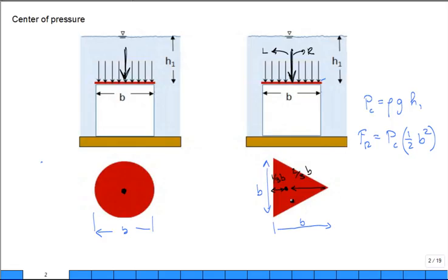How many people remember 1/3? Yeah. Now, how did we get the 1/3? How did you calculate it? Sum of forces. That's how we got the magnitude of F. FR, I'm trying to use some notation out of statics, the resultant force. You had a distributed load, you replaced it by a point load, and you chose the location of where to put that point load by a moment balance. Moment balance. And you could do a moment balance about any point, it'd be equivalent. Okay?